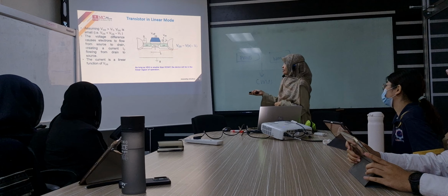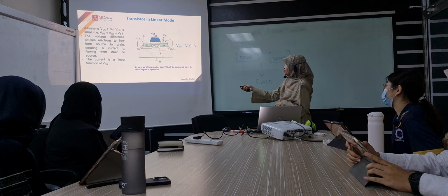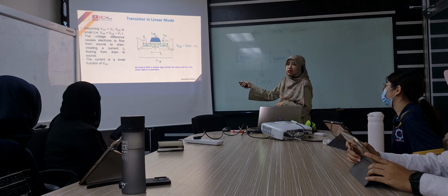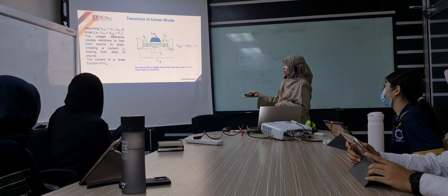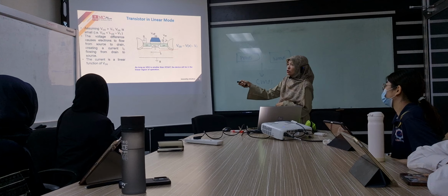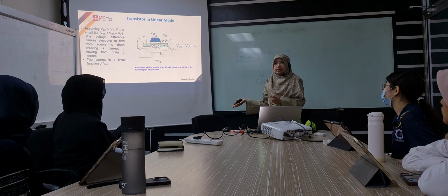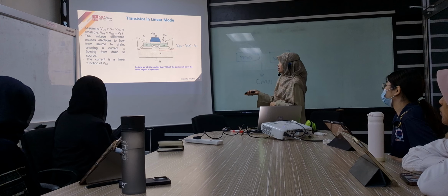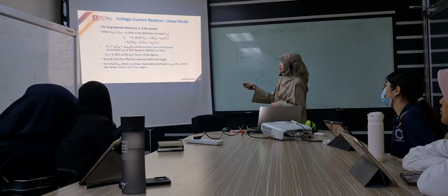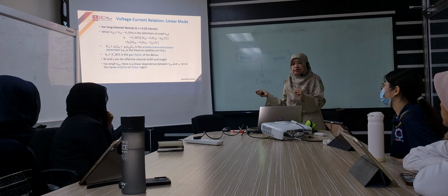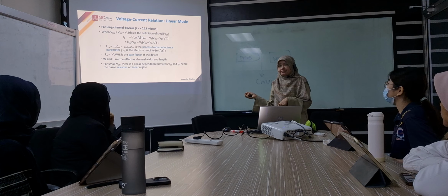Okay, look at how the current flows from one side to another side. We apply the voltage there, and then another drain and source voltage. So normally we will apply these equations to determine whether it's working in the saturation region or linear region. So let's look at these equations. We have two types of MOSFET, one for long channel, another one for short channel.